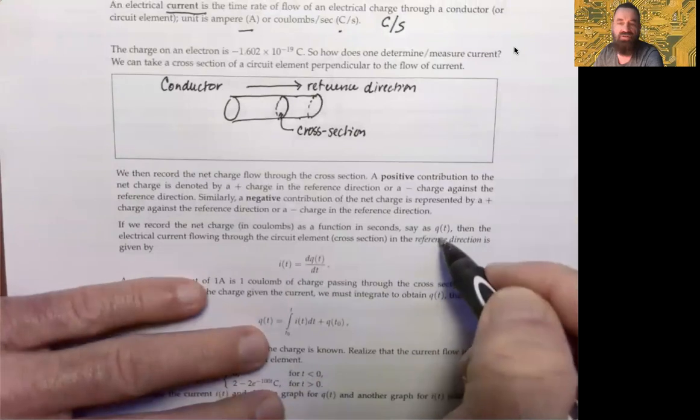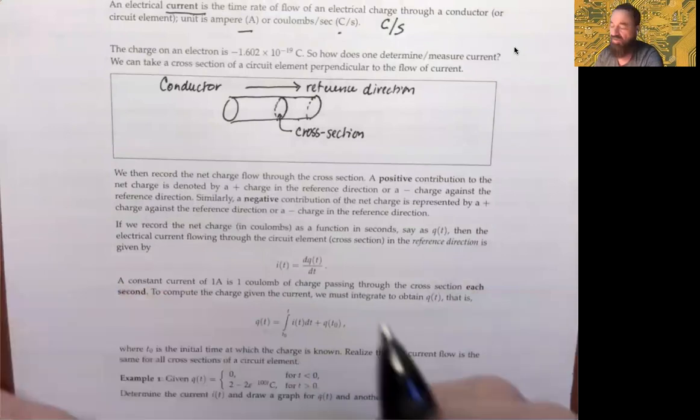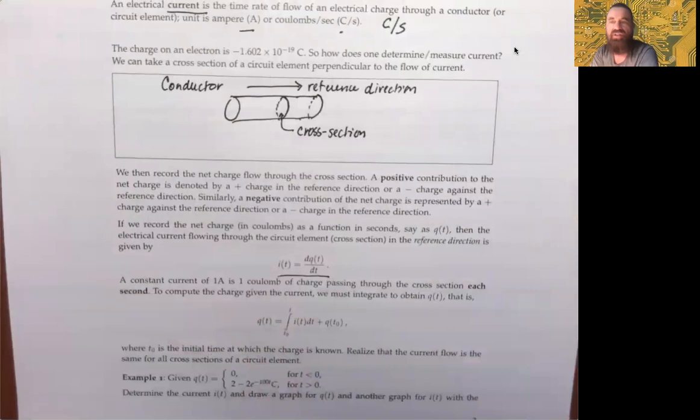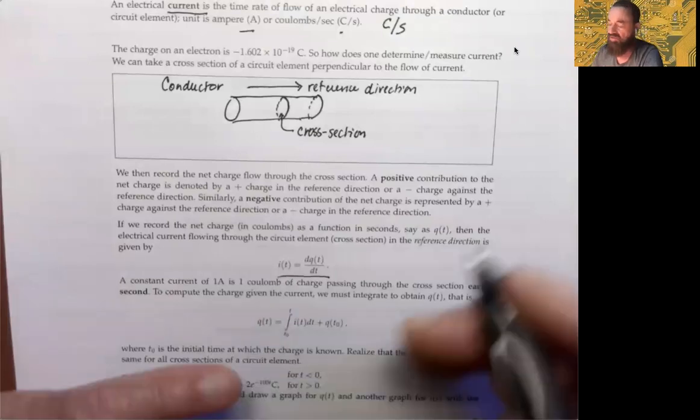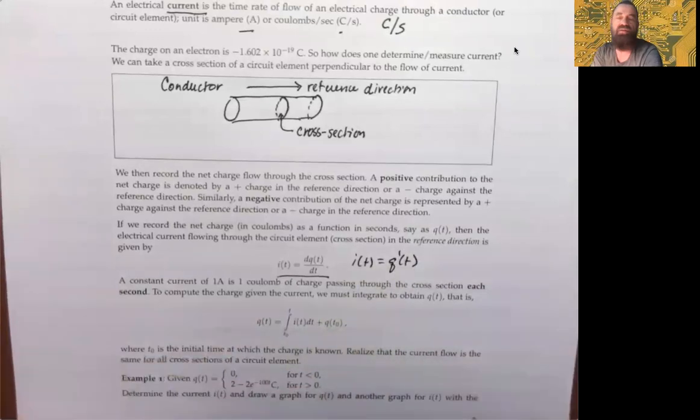So we typically represent charge by Q, little q, and as a function of time it would be a function Q of t. Fundamentally, current is simply the rate of change, and we know from calculus another way of representing the instantaneous rate of change is a derivative. So current, indicated by lowercase letter i, as a function of time would be i of t, and it's simply the first derivative of that charge function. So we could also write i of t is equal to Q prime of t, using the same notation you're familiar with in calculus.